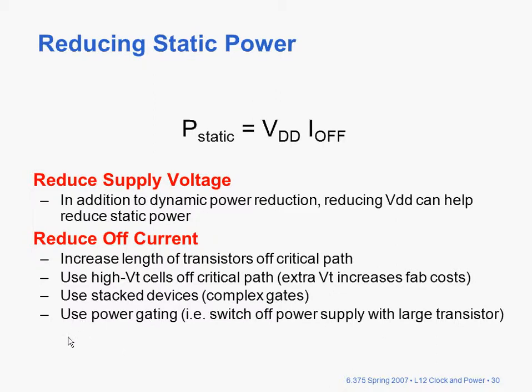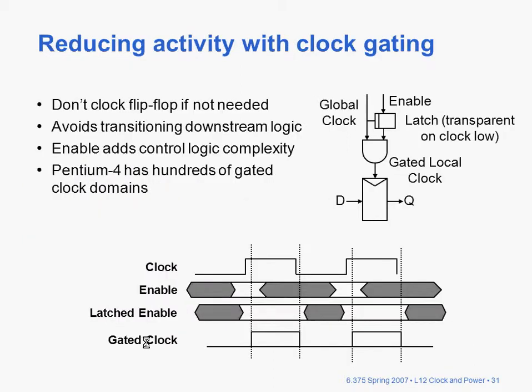And then there were a couple others. I'm not too sure what the stacked devices means, but the other is to use some power gating, where you basically switch off the power supply to parts of the circuit that you're not operating at that point in time.